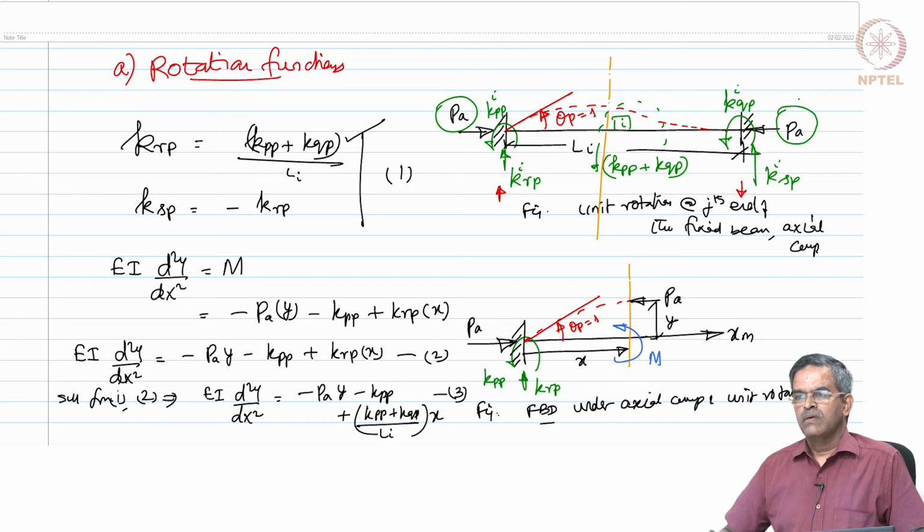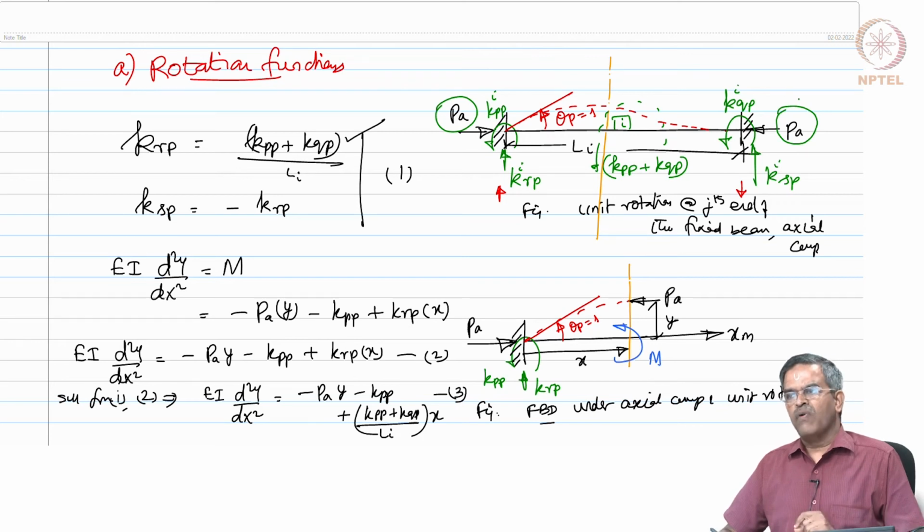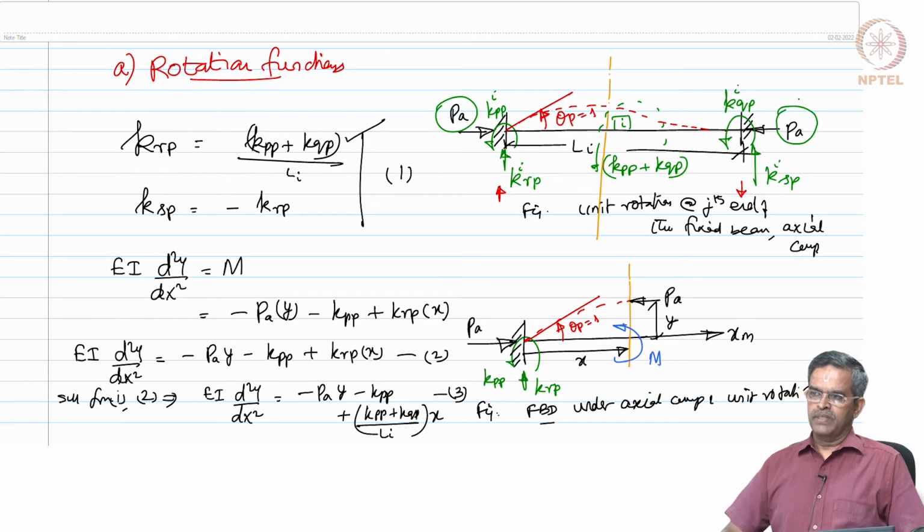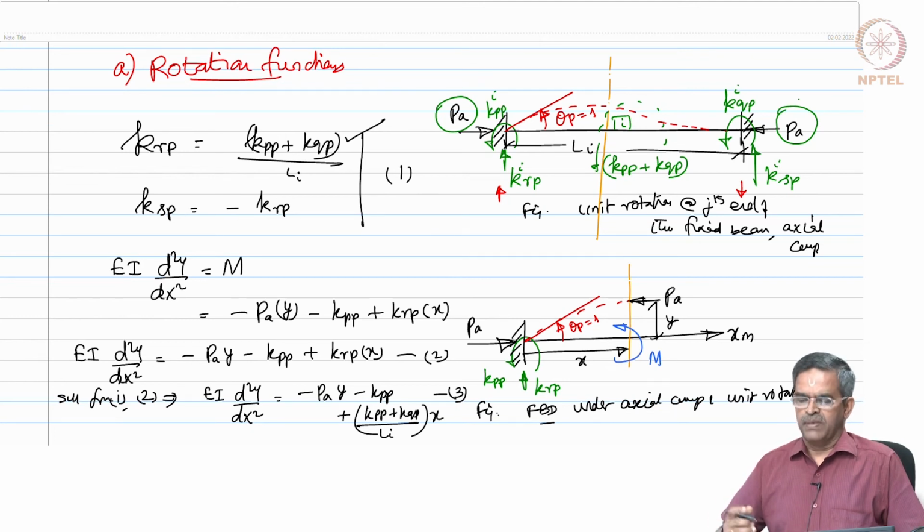That is very good. We are estimating that load which is going to cause failure. So, we are expressing that load PA as a function of Euler's load. If that load PA exceeds Euler's load, it will fail, and that failure will be called buckling failure. That is what Euler stated, is it not?